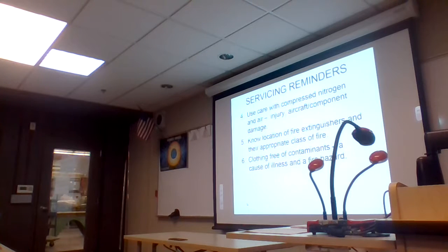In addition, some of the fluids are more than just a regular nuisance. In the case of some of the phosphate ester base fluids, they're an extreme skin irritant. They'll dry your skin tissue out significantly, and boy, it's painful to come in contact with it. The trade name of one of them is Skydrol. You have to be very careful with that stuff. I don't like it. It's great for aircraft and great for fixed installations for hydraulics, but again, it's the last thing you want to get in your eyes, the last thing you want to get on your hands.